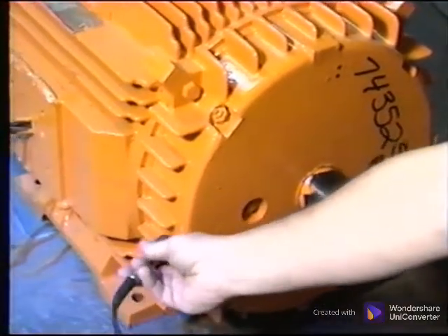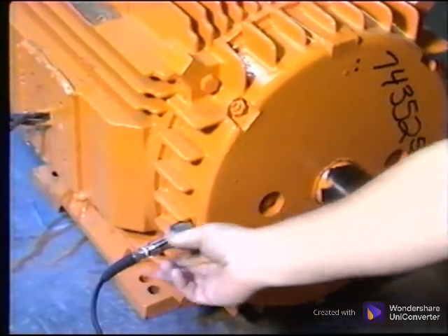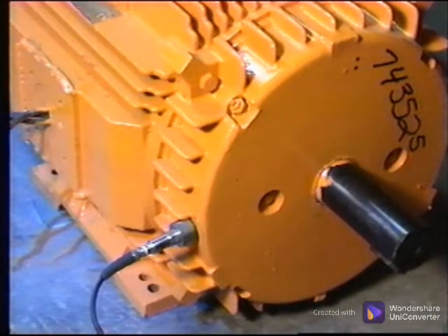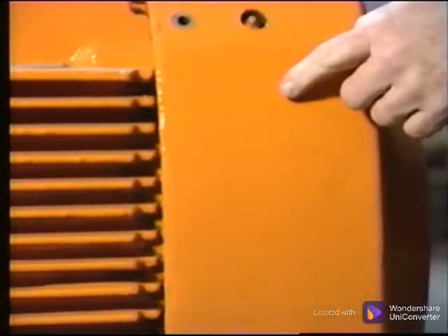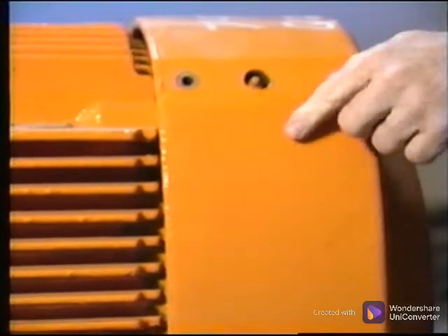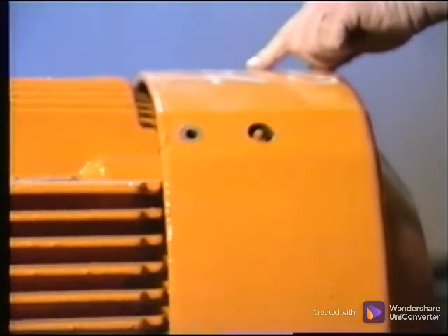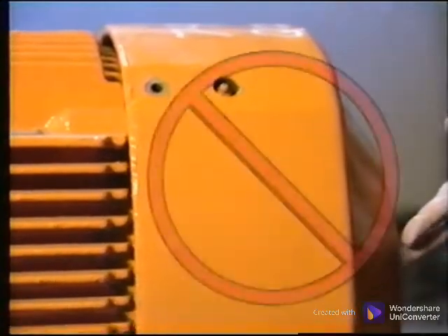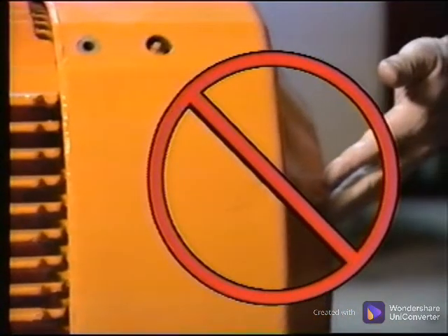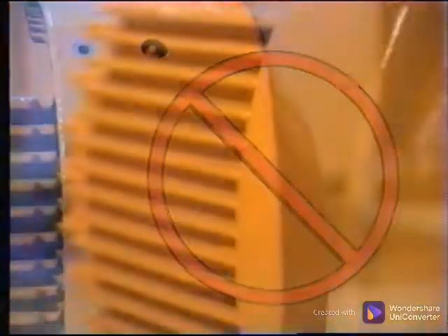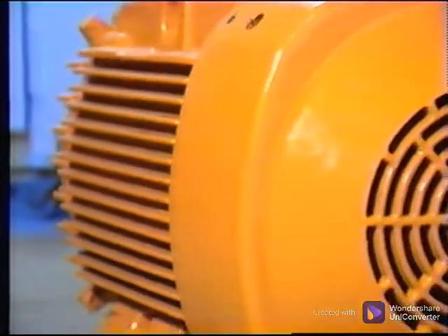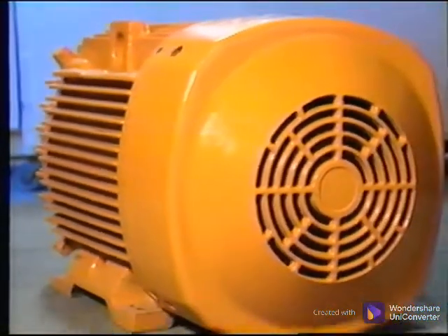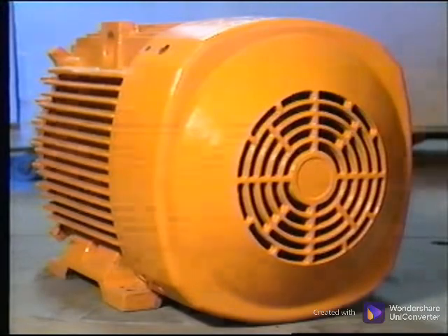If the machine has a smooth area, such as this one has, the magnet mount can be placed directly on it. The outboard end of this motor poses a special problem. The only smooth area is on this fan cover. Using its surface for mounting does not give an accurate picture of the motor vibration, but simply the energy of the cover, which may be transmitting only a very small portion of the actual machine vibration through it.